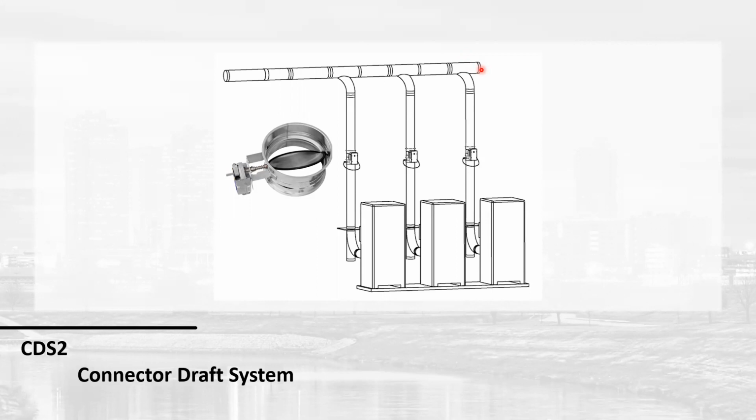And so what I was able to do was put a fan, ran that fan at a deep negative to make sure we exceeded the deepest negative needed, right? Made sure everything stayed negative in the common. But then the boiler damper said, no, we're going to choke that down to maintain that back pressure, create back pressure at the boiler, which is what the boiler was commissioned to, which means it always had perfect draft. It always had the best scenario for combustion in that appliance.